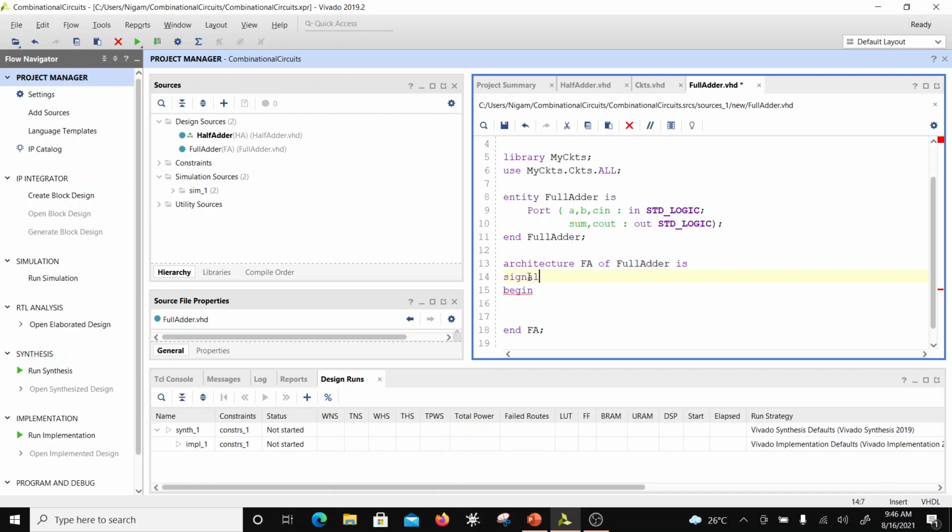The signal is driven while a variable is assigned, right? Variable is assigned immediately because there is very little delay when you put something in the memory. But when you have a wire to drive, then it depends on the driver, right? And a lot depends on the driver's strength, right?